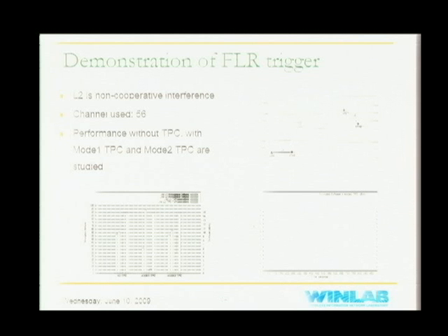This is the transmit power used. In the next graph, we can see that if we are using mode 1 TPC, which is based only on RSSI, link 1 uses the lowest possible transmit power, which is 1 dBm. Link 2 continues to operate at maximum power, but there is a disparity in terms of channel access.